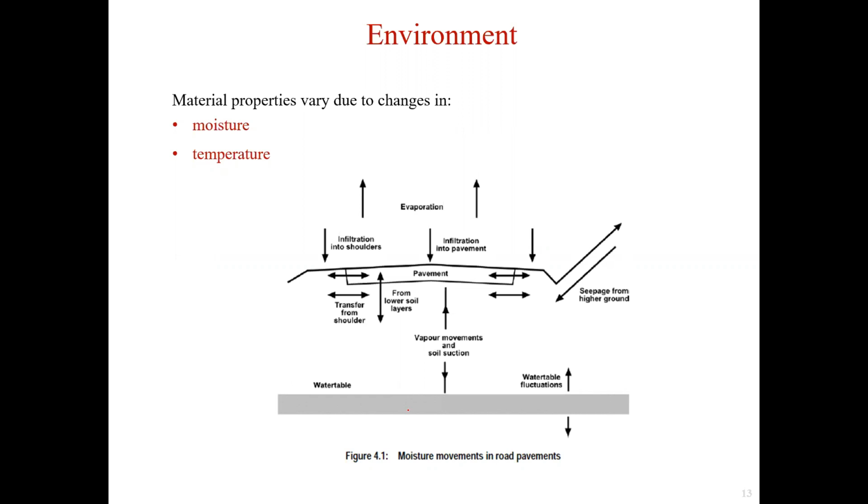Temperature environment also has a major influence on the performance of pavement. For asphalt surfaced pavement, the asphalt becomes stiff and relatively brittle at low temperatures, when it is susceptible to fatigue cracking. But it is soft and viscoelastic at higher temperatures, when it is susceptible to permanent deformation.